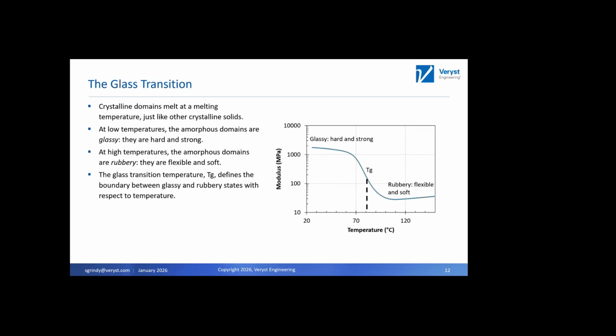So in my experience, it's important to be really careful around the glass transition temperature of your material, because the functional softening of the material can happen at a different temperature than the nominal glass transition temperature. And also there's almost like this window, let's call it from -60 up to probably about 100 degrees Celsius, where you have this extreme temperature sensitivity of the modulus. That means that a small change in the temperature of your material will result in a large change in the modulus. And so you can have wildly fluctuating material properties around your Tg. It makes it really hard to make robust predictions about how your device is going to perform.